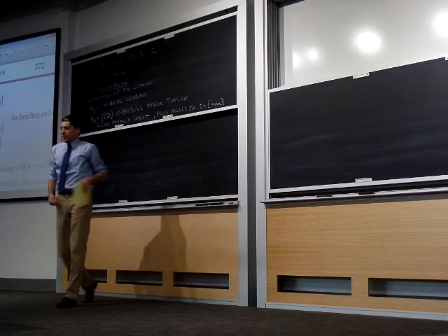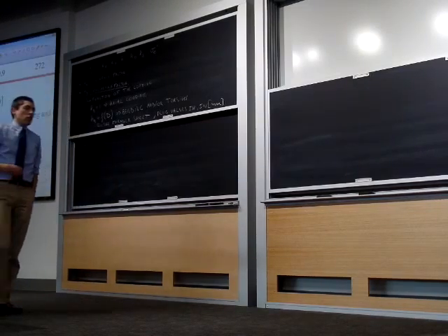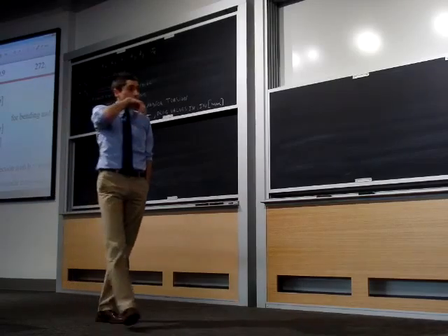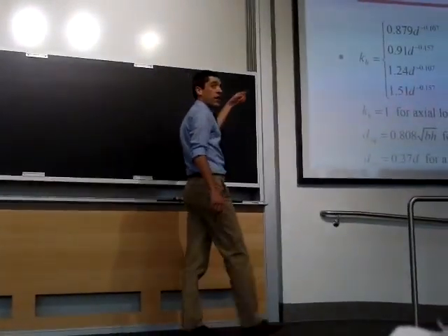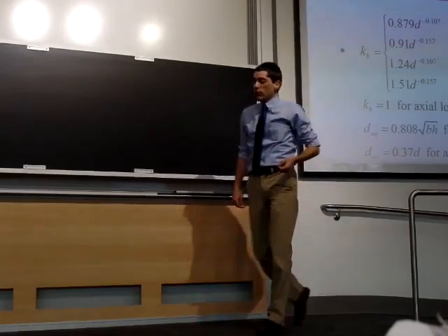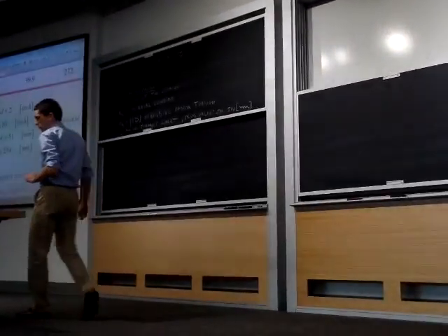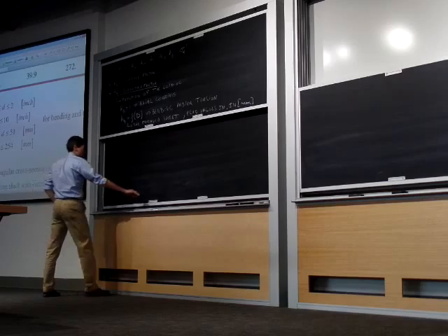Sometimes our shaft is non-rotating, or even non-circular. The equations that you see here are only for rotating circular shafts. So if we have a non-rotating or non-circular shaft, we need to do one little tweak before we can use those equations, and we need to calculate an equivalent diameter.